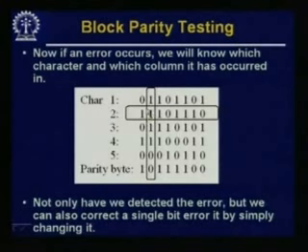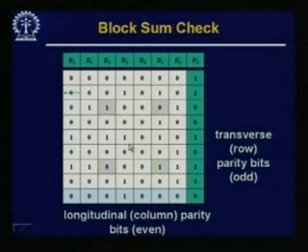So, this is another, just better diagram for this. We have got this system. So, this is using say odd parity. I mean there is no reason to use the same kind of parity in both the cases. You can use odd parity for the transverse parity bits for these, and you can use even parity for these and calculate this. So, if there is some error, we can compute it.